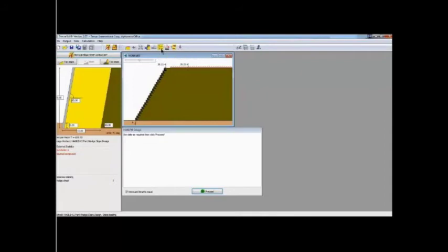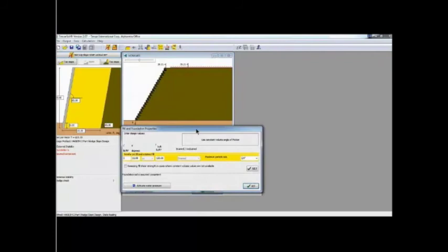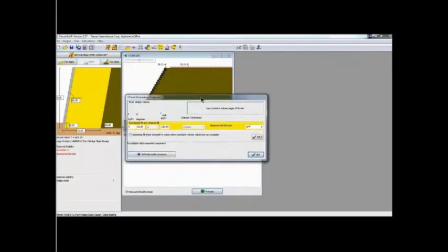The next item to check is the soil properties. This box is a little bit different than the retaining wall designs. You can see we have just one type of fill to enter, because for reinforced slope design you'd be entering the weakest soil properties that you have. So it's assuming that your foundation, your reinforced fill, and retained fill all have the same properties. Another important note is that we're now using the constant volume angle of friction.